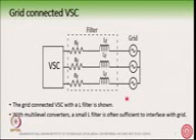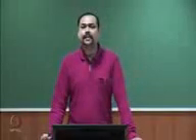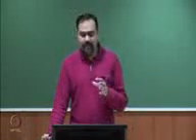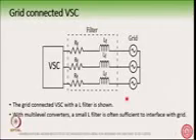The L filter is the easiest filter. It is basically an inductor, in a 3-phase system a 3-phase inductor, and the RF shown in the diagram is nothing but the resistance of this inductor.